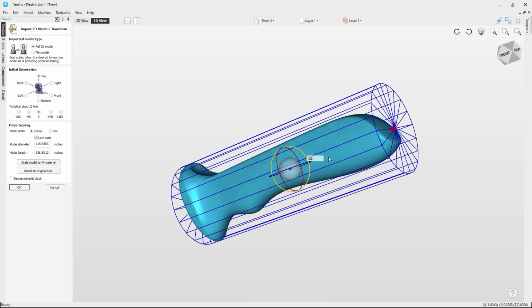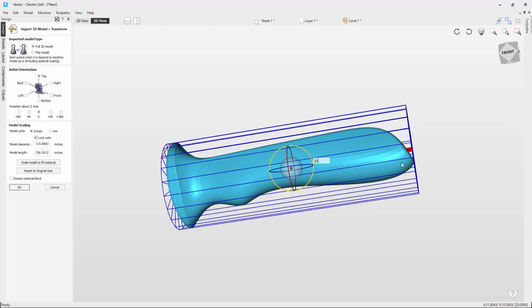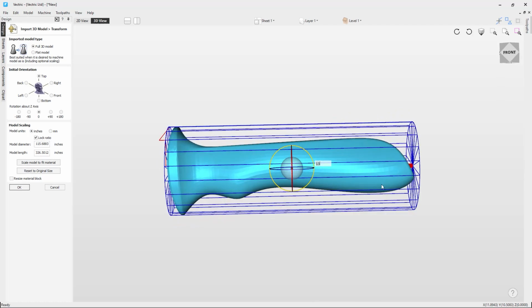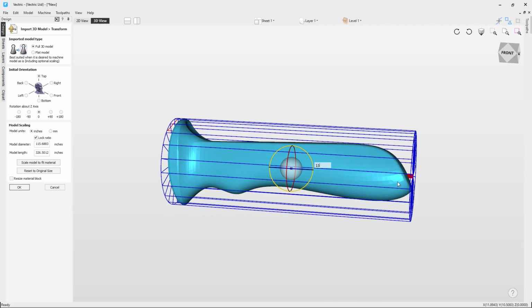When the software unwraps this, it will try to generate material underneath this area here, where the axis is and where the next part of the model is. We don't want that, because we want the least amount of undercuts possible so that every bit of the model is represented. If you were to import something like a figurine, for example, this is where you may find some difficulty. You may need to establish another methodology, because some models unfortunately will have undercuts no matter what you try. But in this case we can try and get rid of them, so we will do that.